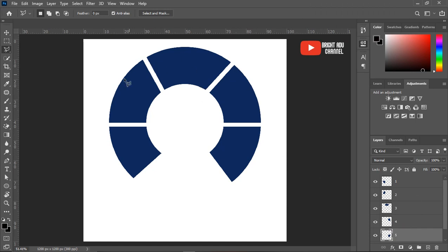So now all these things you see here exist as separate layers. So this one exists as a separate layer, same as this one, same as this one. The little move you do will spoil or change the shape of the perfect circle you had already. So in order not to get any unfortunate movement within the shapes, let's select them all. We'll first click on the 1, hold the shift key, then click on the 5 to make the selection among them. Then you link them so that any movement you do will affect the whole circle, though they exist as separate layers.